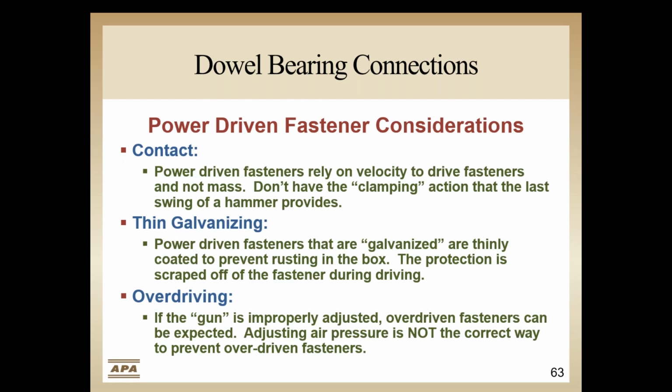We mentioned that there are different sizes of nails that could be specified to get the intended capacity of the connector. We also need to consider some other factors. First being contact or clamping. Consider that a hand driving a nail also clamps the material together as you drive the nail, whereas a power-driven nail uses velocity to drive the nail, so it doesn't have that same clamping action that pulls the materials together. So in using a power-driven nail, the installer must make sure the materials are clamped together when driving the nail.